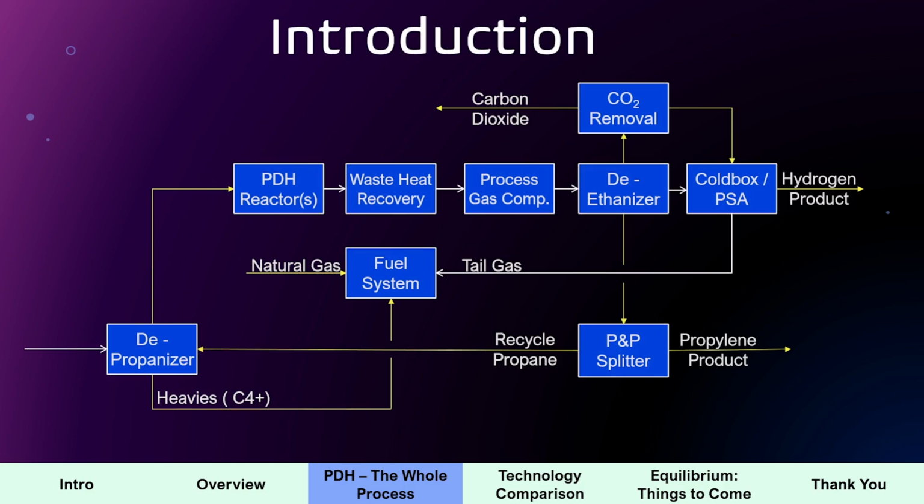The closer these boiling points get to each other, basically the tighter the difference between them, the more trays I'm going to need. So that's number one. That's the basic thermodynamic principle: the closer the boiling points, the harder it gets, or basically I need more separation stages in order to separate them. That's assuming ideal behavior. If we are talking about isotopes or something, that's going to be a different discussion.